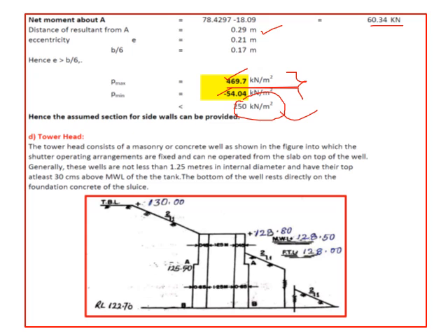And then, if it is very near to the bund, here the top of the bund is very near, steps can be provided here, and a person can come here and regulate the gates. Otherwise, if it is a little bit far off, then you can extend this to the top and provide a footbridge somewhere here like this. So a footbridge can be provided and this can be extended up to the top. A person can come here and regulate. So this wall has to be extended right up to the top of the bund. But if it is very near to the bund, steps can be provided. However, a person operating can come here and regulate the gate.